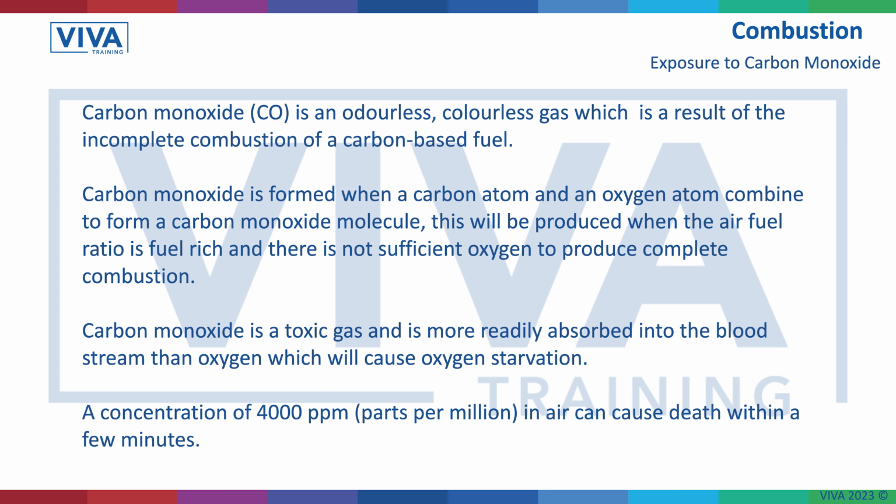So, carbon monoxide, totally odourless and colourless. That's the result of incomplete combustion. It's formed when a carbon atom and an oxygen atom form that carbon monoxide molecule. It's typically when the fuel-air ratio is fuel rich, with too much fuel, not enough oxygen. And it's toxic and it gets absorbed into your blood.